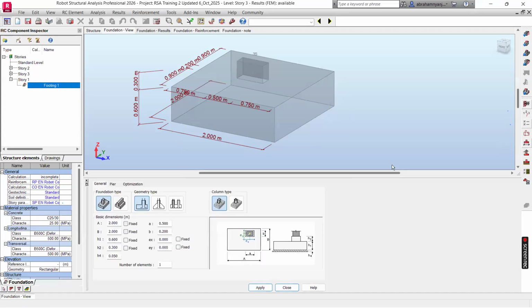These ones, item dimensions, you're familiar that it's these ones that are open here. So for example, when we go to the journal, this shows the foundation type. So you can have the strip and the different dimensions. As I said, by default, it comes with a 2 by 2 by 0.6, what is displayed here. This column is automatically captured from the model. It should be similar to the column that is attached.